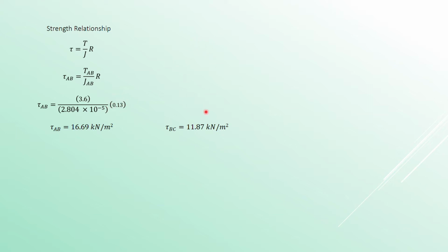And then, if I'm not mistaken, this section is also the same. Please take note of the radius here. It is the radius, not the diameter. Based on the mistakes that I have made, be careful when you are solving your problems. The mistake was made by me, so you have to correct it. For the polar moment of inertia, or the second moment of area, you use the diameter. For this one you have to use the maximum radius. So 0.18 is wrong also. It should be 0.09. Please make the changes.